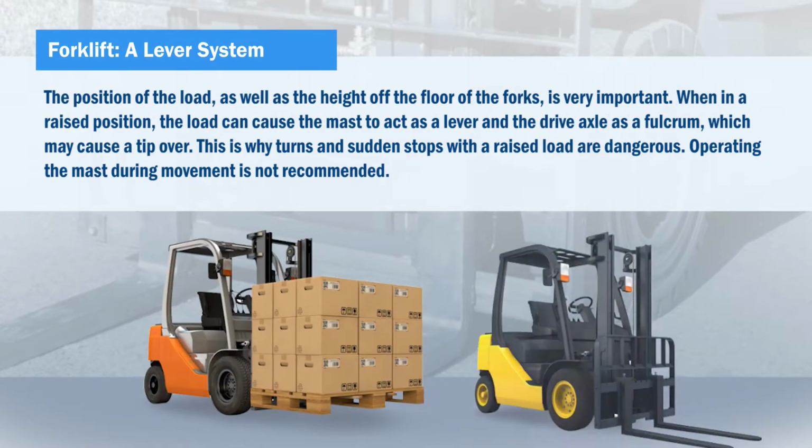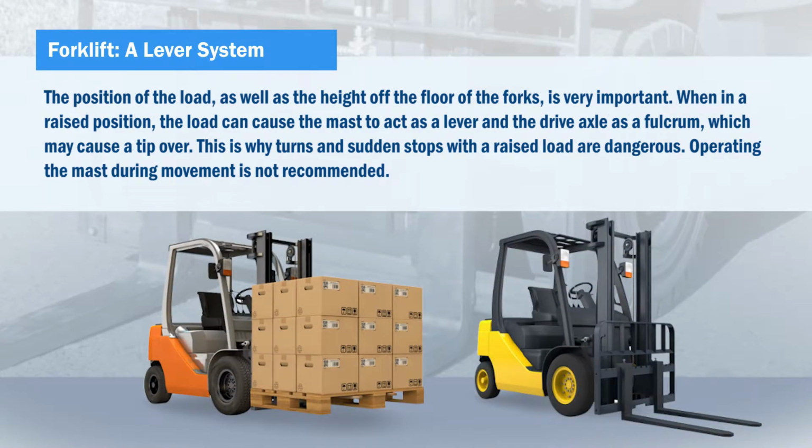Forklift, a lever system. The position of the load as well as the height off the floor of the forks is very important. When in a raised position, the load can cause the mast to act as a lever and the drive axle as a fulcrum, which may cause a tip over. This is why turns and sudden stops with a raised load are dangerous. Operating the mast during movement is not recommended.